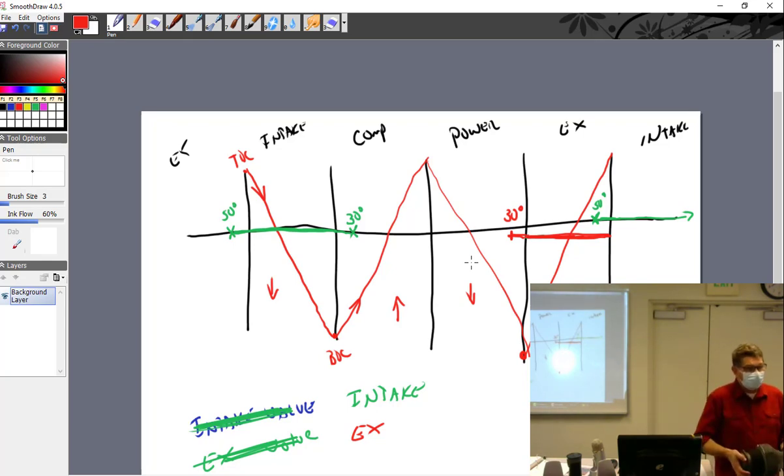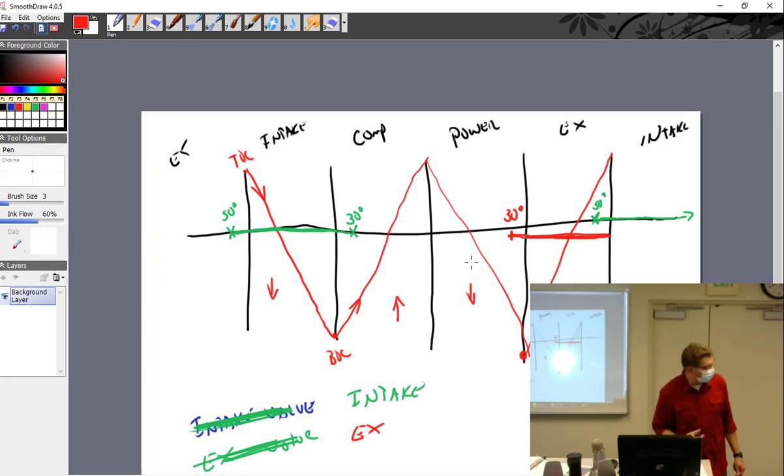Why? So what's that going to do if we just trap it in there and hold it? It's not doing work. Dissipating heat. Yeah, it's slowly dissipating. It's just making this hot. How hot is it going to get if we just kept it in there? 1400 degrees. Well, this is going to melt down at that, because red line for this is around 400 degrees. So we don't want that. If it's done doing work, get it the heck out. And that's the whole idea. As soon as we figure out it's done doing its work, open the valve, get it out. So that's why it's early.